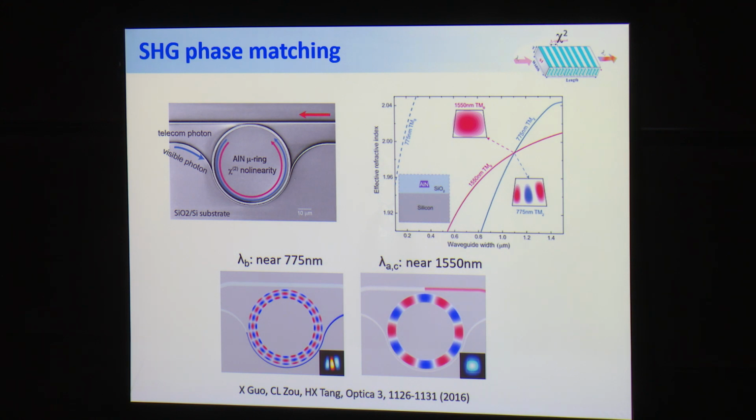So you have two modes supported by this ring resonator. One is the fundamental mode here, one is a higher order mode at 2 omega frequency. Now, you need to design a launching waveguide to excite the fundamental mode. This is the coupler down here, that's phase matched to this waveguide. You also design a second waveguide here, which is much narrower, to phase match to the second harmonic mode. In this way, you can excite this resonator with fundamental light and extract second harmonic light.